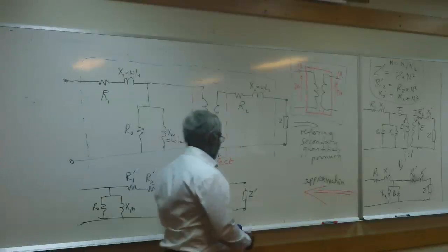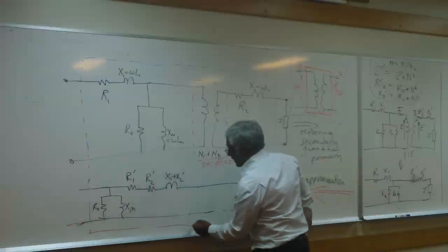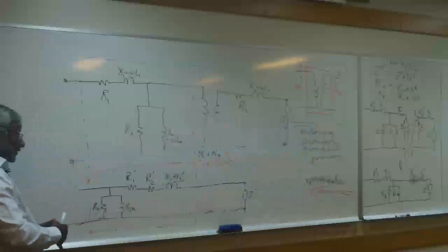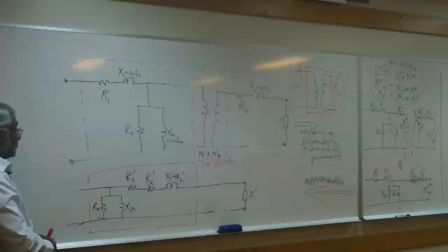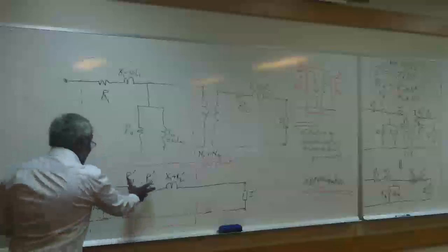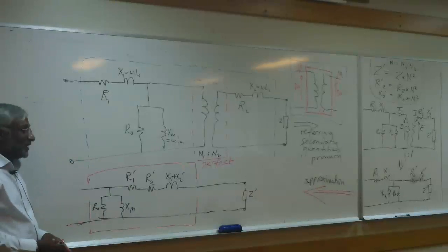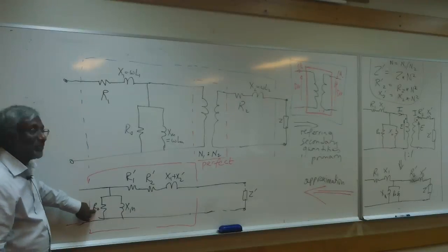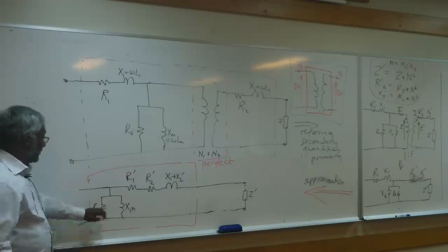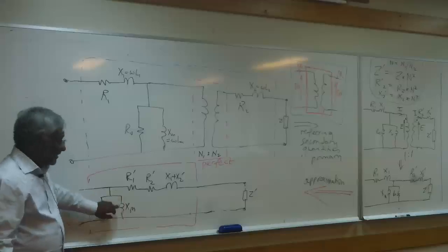See, this is the transformer here. We're calling this a transformer. It's a perfect transformer plus imperfections. So in here is a perfect transformer, 1-to-1, because we have converted everything to 1-to-1. As you look in this box and you say, make everything perfect, you will see you get just two wires. So if you make the transformer perfect, what happens to R0? Infinite. So no connection there. Similarly, the magnetizing current would be 0. So this is infinite. So this goes away.